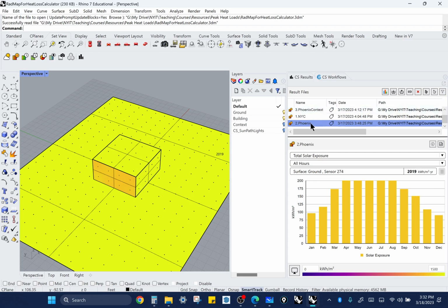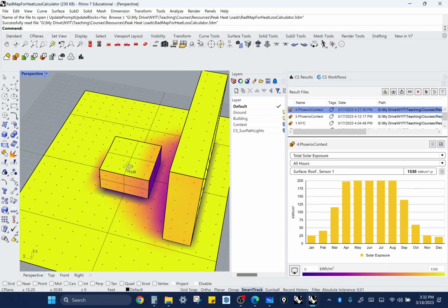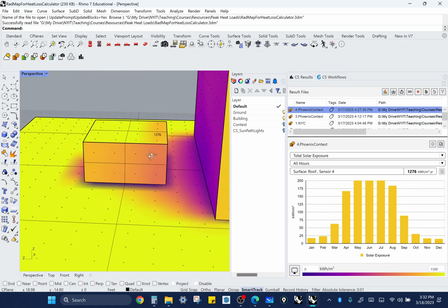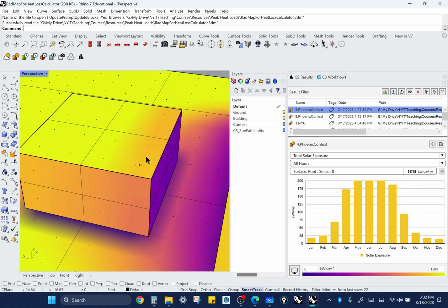And also, if I were to add context to this, for example this big tall building, so if I were actually on a site that had some kind of obstructions or context, now I'm talking about a much lower amount here, right? Because I'm getting a lot of shading, and it actually changes between the front and back of the roof. So if I had PV in this situation, I might want to focus it back here at the back because I'm getting more sun there.